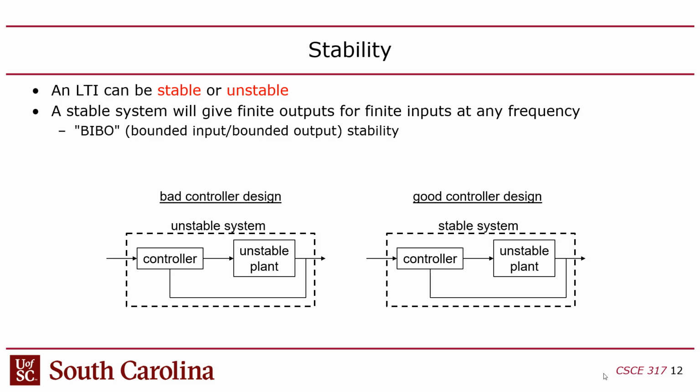Okay, so control systems have several properties that you're trying to achieve when you design them. The most basic of which is called stability. You want it to be stable, meaning that if you give it a bounded input, and by the way, what is the input here? The input is the set point, right? So the top level input is basically like the cruise control setting on your car, right? And then the output here is the state of the plant, right?